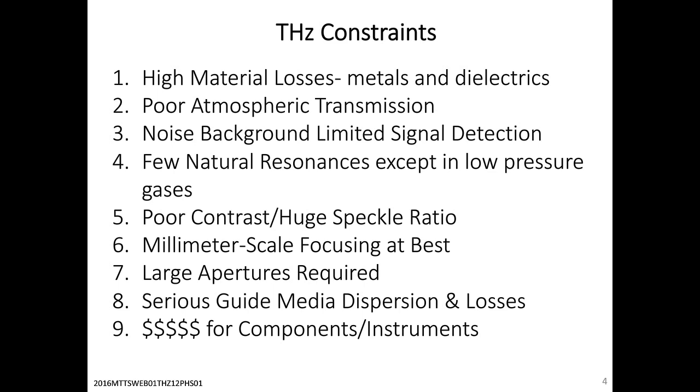There is no such thing as the equivalent of optical fiber in the terahertz range because of the interaction with phonon modes in dielectrics and because of the high ohmic losses in metals. So you can't propagate terahertz energy in any material without suffering significant loss, whether that be a metal waveguide or whether it's a quartz substrate or a polyethylene substrate, which has low loss but not very, very low loss compared to other frequency regimes. So that's a very big limitation.